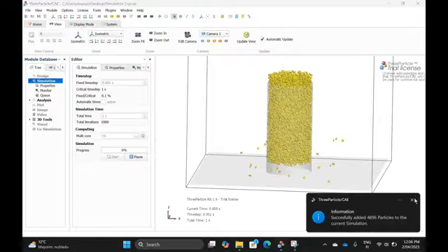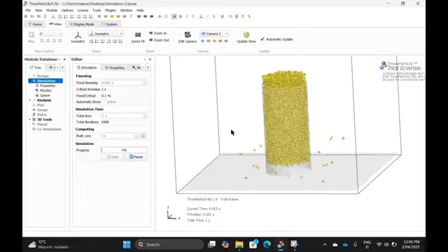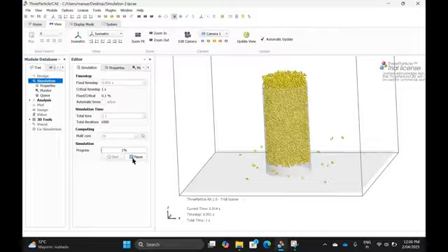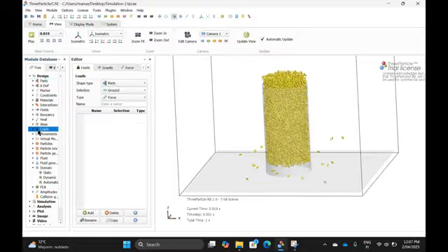Design. That's also a very common mistake a lot of people don't think of. Loads, there is no gravity step. On loads, there is a bar that means gravity, and you need to have gravity in the z direction, minus 9.8 or whatever. Save. And now, let's try it again.